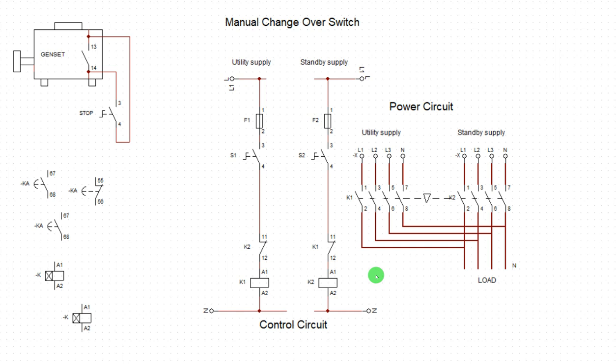Listen to the voice note. Let me repeat again. When I go to the genset and start it, I don't want this genset to supply power to the load immediately. I want it to time for a few seconds before this contactor closes and gives me output.